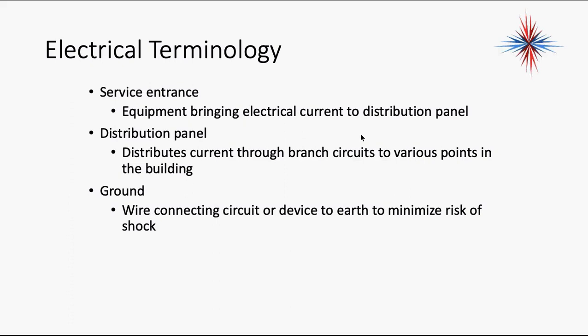Service entrance is very important to find on your blueprints. Even when you're installing HVAC systems, you have to find the service entrance if the building is just being built. The service entrance is where we bring the power in from the outside into the breaker panel or distribution panel. The reason we need to find that is you're not allowed to put any equipment within 36 inches of a service panel, or service entrance.